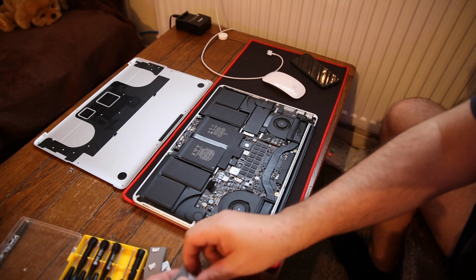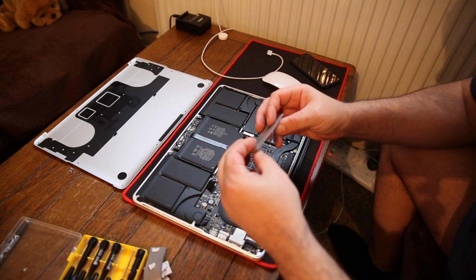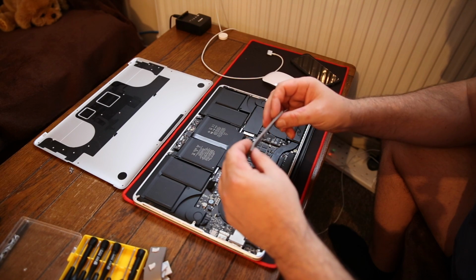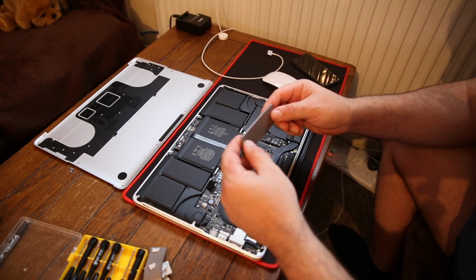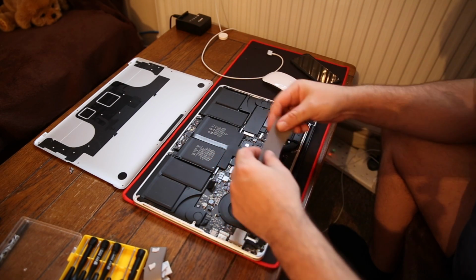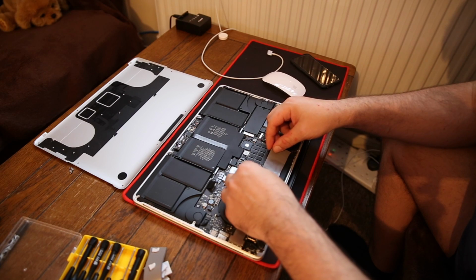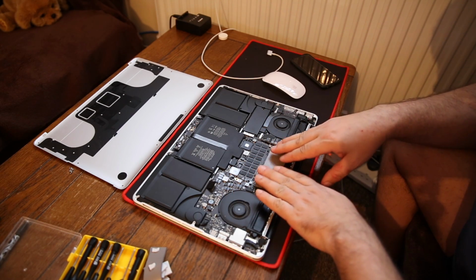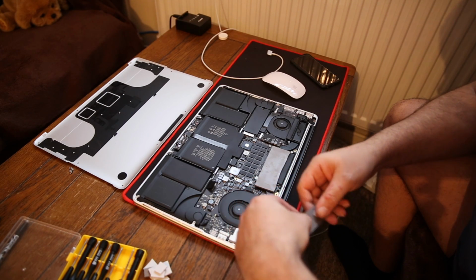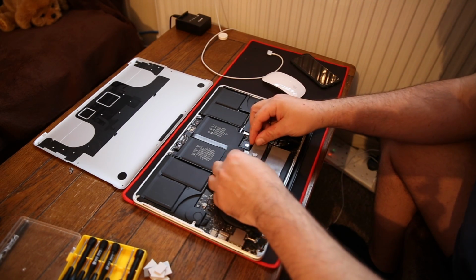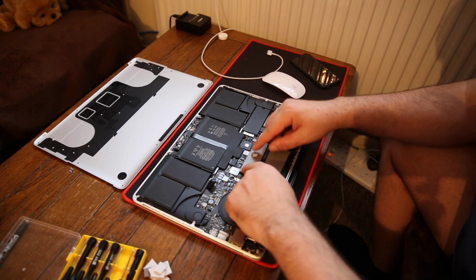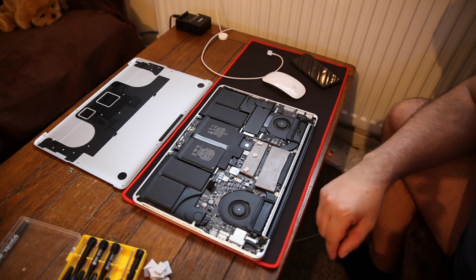And I'm using a special component, some thermal pads you can find on eBay. These are cheap, probably around £2 each, a big 10 by 10. I'm using them over the processor and the graphic chip, so this will touch the back cover, and also for a few more things on the RAM, and I just use this to keep it pressed to be sure it's not moving.